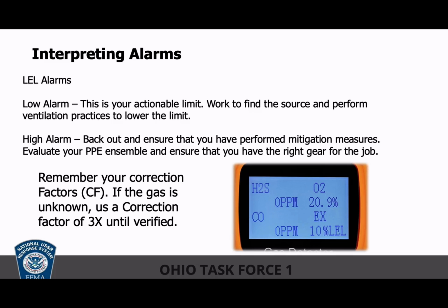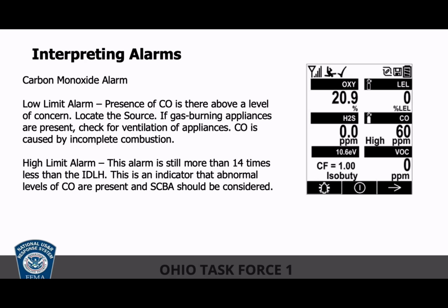So in unknown gas concentrations or unknown gas amounts, I always say, hey, listen, on the correction factors, multiply it by 3. That's a good conservative number to keep you and your team safe. If you know what the gas is, apply the correct correction factor. In the task force, our MultiRAEs can easily be opened up and we can apply correction factors on the fly and correct for the known gas that's with us.